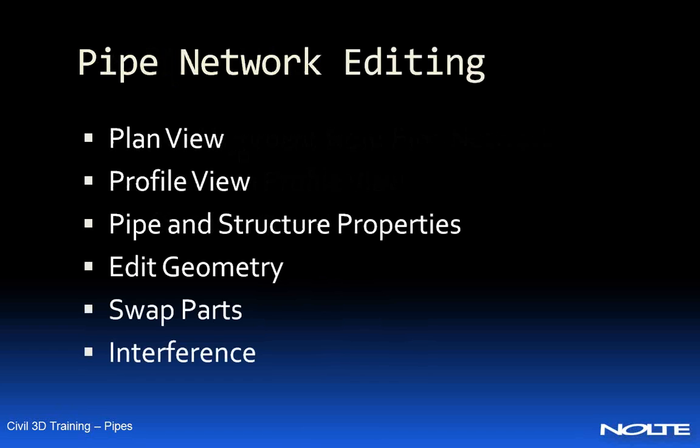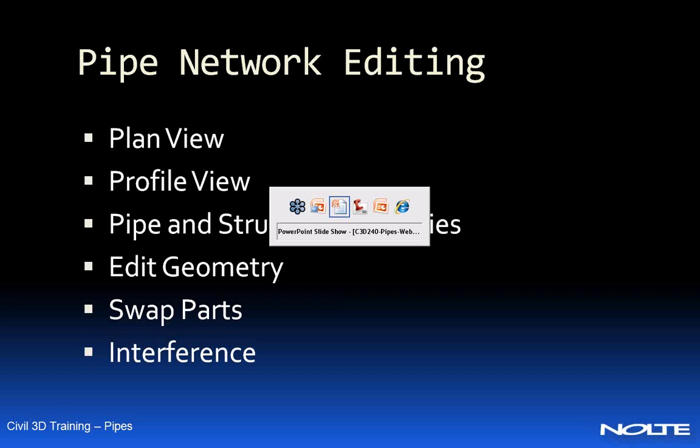Now in terms of editing, I've already showed you a little bit in plan view. We can grip edit, we can move things, we can right click on objects and bring up their properties. Now in profile view, I can't move them in the X and Y, but I can modify inverts and rims in my profile, and I'm going to do that both through grip editing and also using the pipe and structure properties. We'll also look at the edit geometry command, and we earlier saw swap parts. I think I'm going to skip labeling for today, and we'll finish up showing you just real briefly the interference and the final model that I've created here.